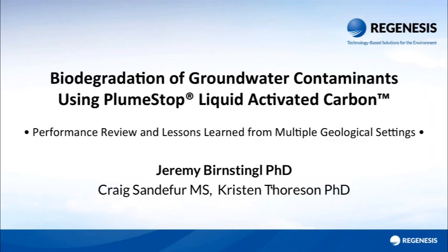Generally, it's not a problem. It simply extends the radius of influence. But if there is a sensitive receptor, property boundary, river, lake, or whatever it may be within an advection distance, then it is possible to lock the PlumeStop in place there and then through injection of a counter reagent, which actually provides a means of dropping the mobile PlumeStop out of solution in a flash. And that's one of the things that we can do with our field application capability.